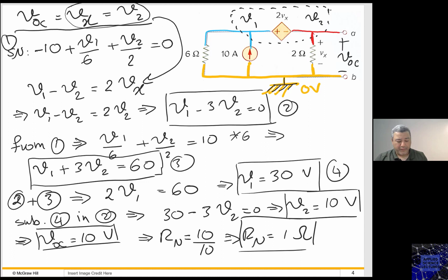Now, if you want to find the Thevenin equivalent circuit for this circuit, you can still find the VOC and find the short circuit current. Then the VOC would be the V Thevenin, right? And dividing VOC by the short circuit current will give you the R Thevenin. So this is not a big deal. This is the general approach, which is basically finding the open circuit and finding the short circuit. So the whole circuit gets replaced by 1 ohm resistance. That's correct. So let me.